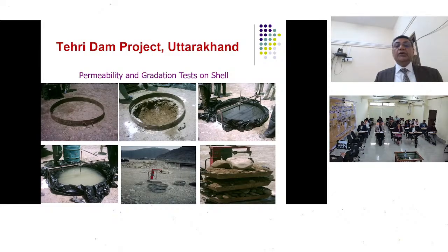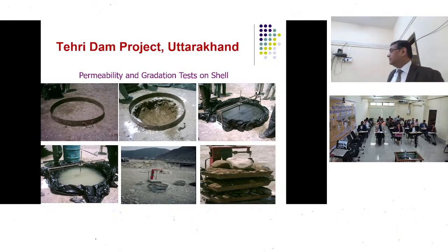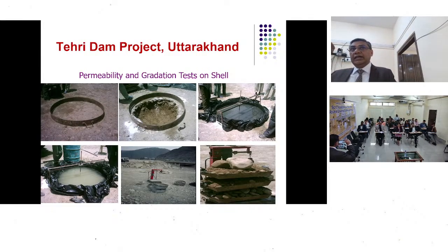Again, for permeability of the shell, as I was saying, it was the water replacement method. So you have a ring and the water replacement method. That was the standard practice being used in the dam. We got these things constructed at the site itself: a bigger ring and then a pointer system, with a pointer having a graduated mark also. So every time you fix that, you know this much is the level of water we will be going in for.